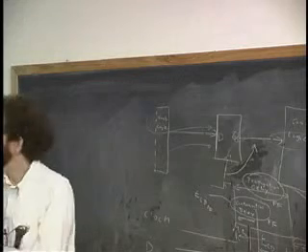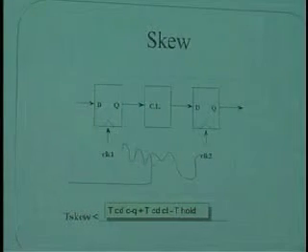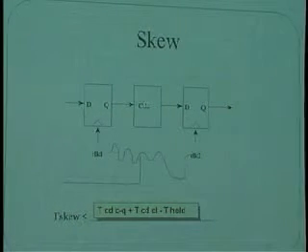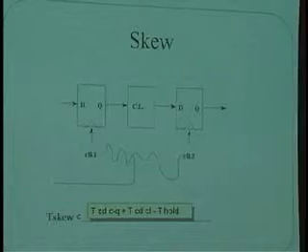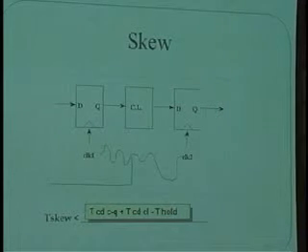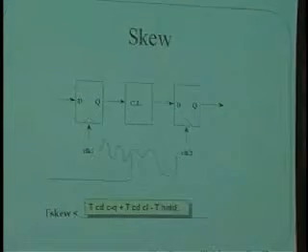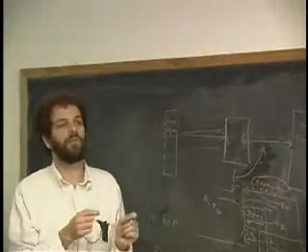Okay. Let's take a look at the final question which was asked, which was clock skew. We've shown a system where all the registers are clocked at the same time. But is that actually the case? The clock isn't perfect. The wires are not perfect. The parts inside of the register are not perfect when they perceive the clock on the input. What would happen in a system if certain parts were clocked before others?